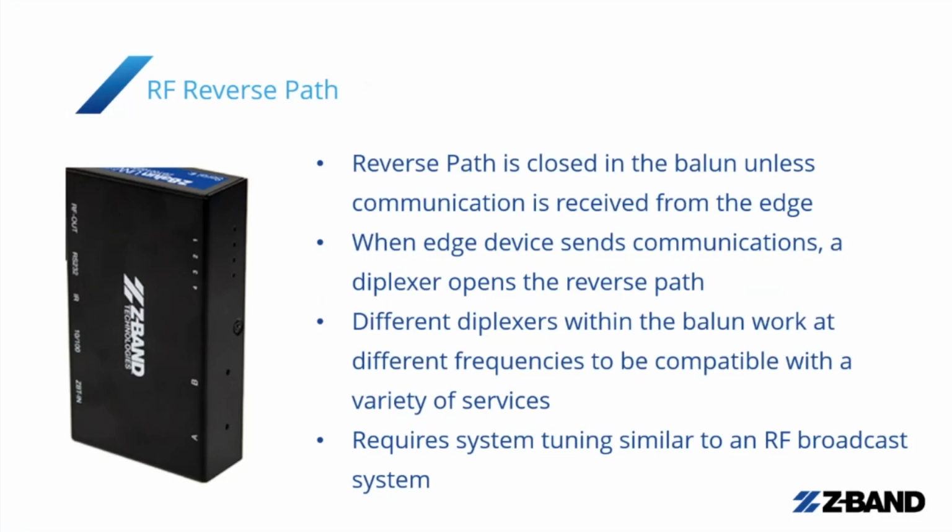And the reason for that is the communications frequencies have changed so much that it's a custom diplexer or a different diplexer than we traditionally used in the previous versions of the platform. Then also the variability within that. We have to know, on a project by project basis or a set top box by set top box basis, what reverse path frequencies it's using and what version of DOCSIS it's supporting. Without the ability to answer those questions, we can't appropriately design a system.